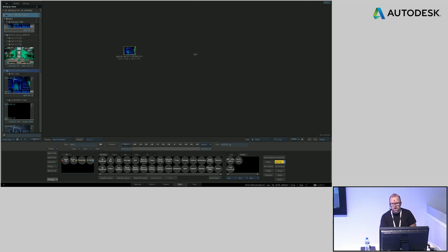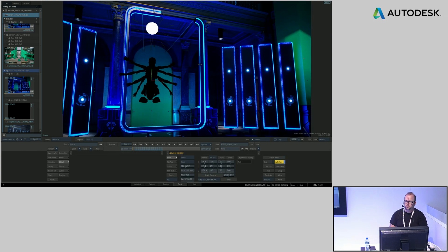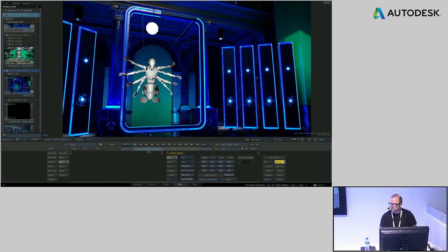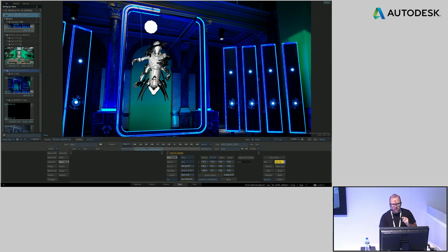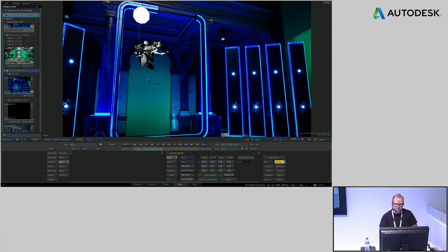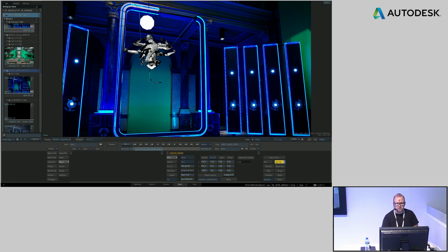The rather innovative method that this artist, his name is Elad Offer there at PsyOp, used, along with the other talented people there, was a way of taking an Alembic cache, which is a moving, deforming piece of geometry that you wouldn't perhaps typically think to use in compositing, more of a pipeline cache format. But the great thing about it is that it's exactly the right shape, of course, to match the underlying footage, but it also can be relit. So that's the great thing about geometry, right?